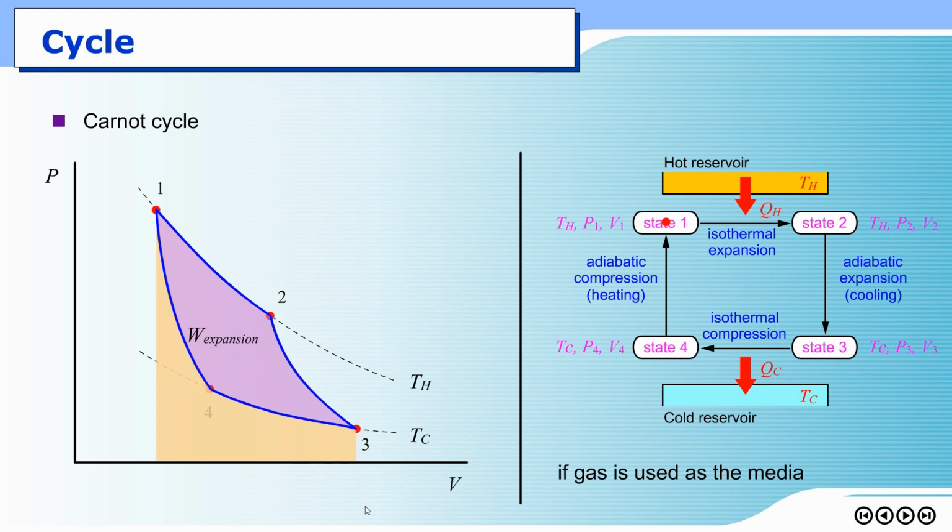So the area underneath this graph is supposed to be compression work. Okay, in this case, expansion work is greater than compression work, which is a little bit different than what I mentioned in lecture 2. This is a special circumstance when we discuss the engine. Okay, so therefore this engine can produce work in terms of expansion work that we can use. The amount of work produced by this engine can be found just by taking the expansion work subtracted by compression work, and that can be represented by this green area. This is the net work produced by the engine.